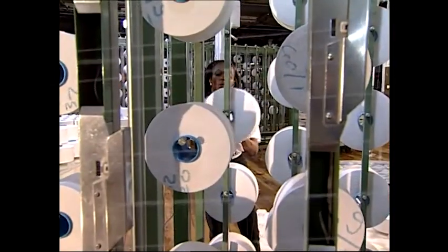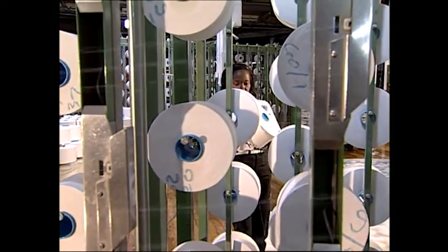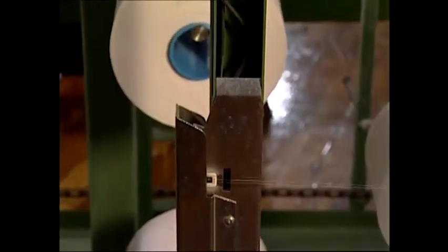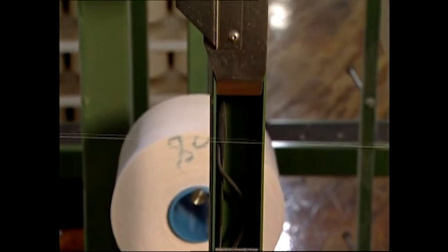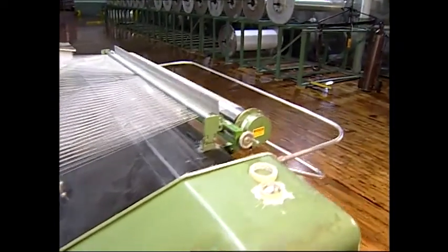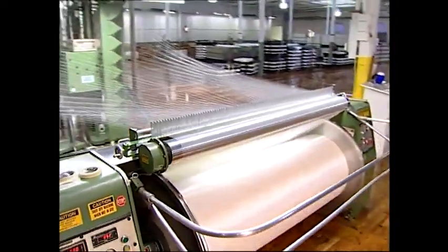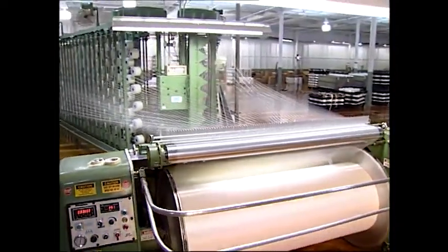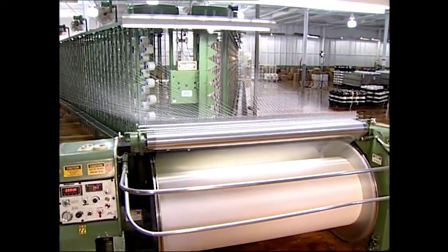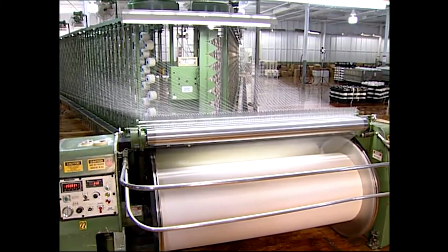Yarn packages are first placed in a creel, from which they are wound onto a section beam or die beam. The path the yarn follows on the creel is through tension devices and stop motions. Next, the yarn passes through a reed or comb that guarantees even spacing and a yarn sheet width that matches the width of the section beam. In some cases, the section beam is perforated for yarn beam dyeing.